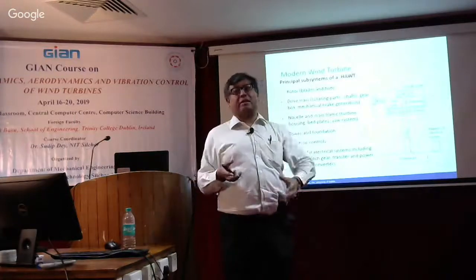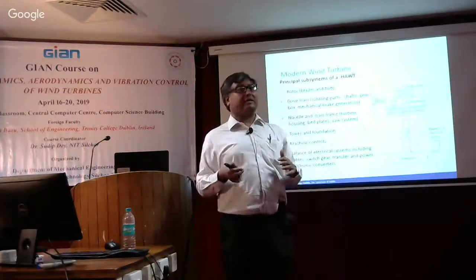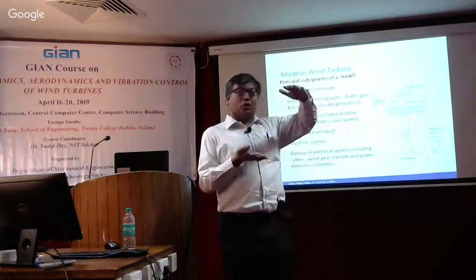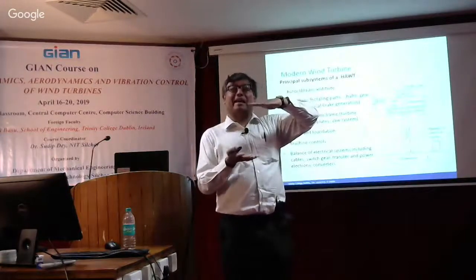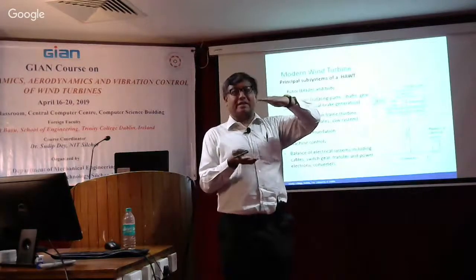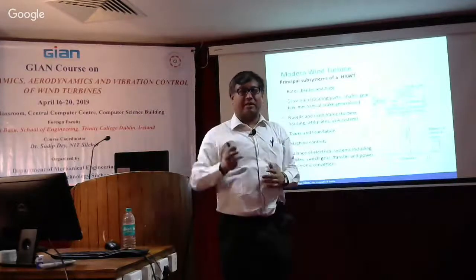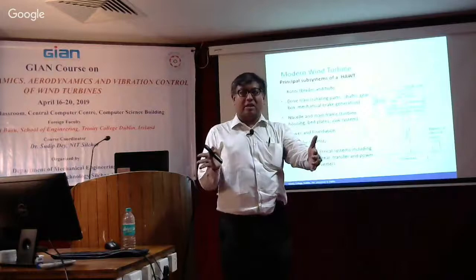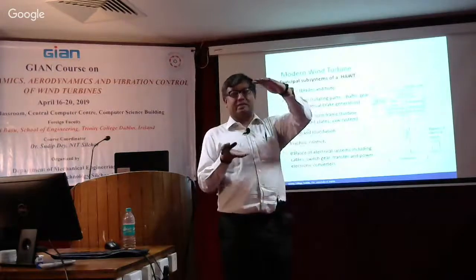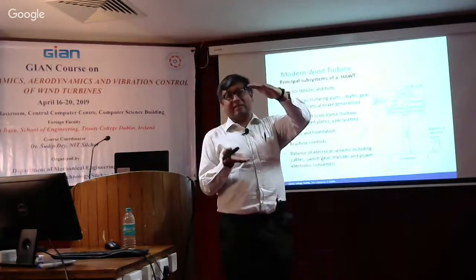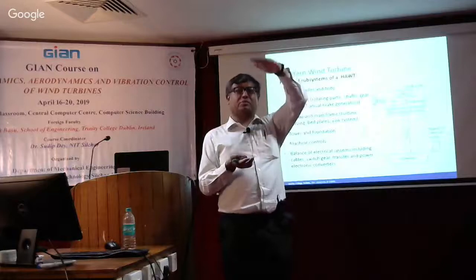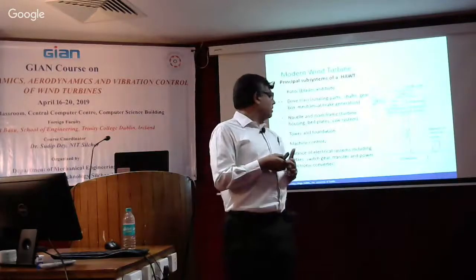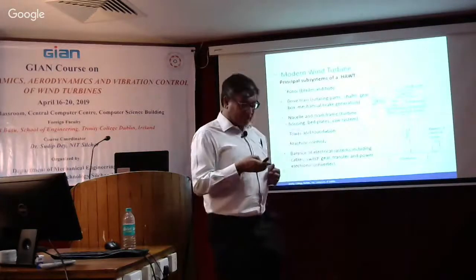And then on the top of the shell, there is a splicing intermediate element put in. And that is done for two reasons: to connect the tower to the foundation, but also to take care of any misalignment. If there's an eccentricity, then that will induce a lot of movement. So to make sure that you have a stable base, you have the foundation, and then there is an intermediate splicing used to connect the tower to the foundation. So I think the problem was there.